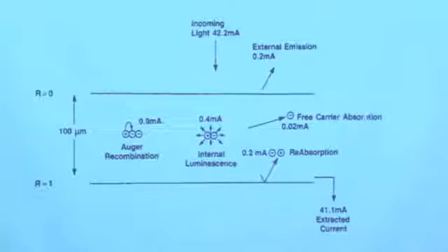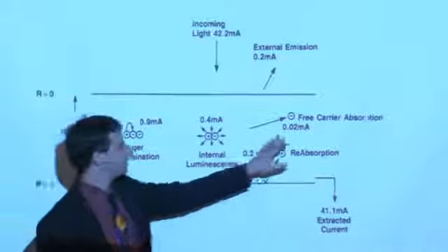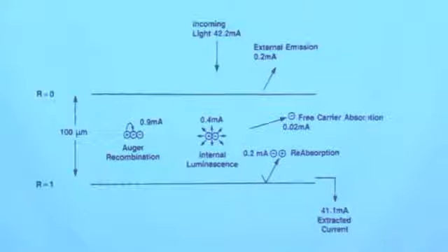So that's called photon recycling because you have a radiative recombination event. It emits a photon inside of your solar cell device, and that photon bounces around a few more times until it's reabsorbed, generating another electron hole pair. And that is essentially the major boost in some of these ultra-thin, high-performance solar cell materials, such as the Alta devices, a record efficiency 28% gallium arsenide cell, is the ability to do this photon recycling. OK?